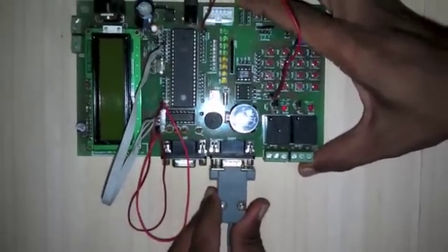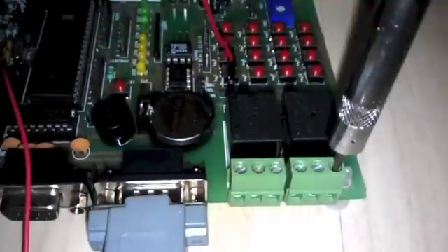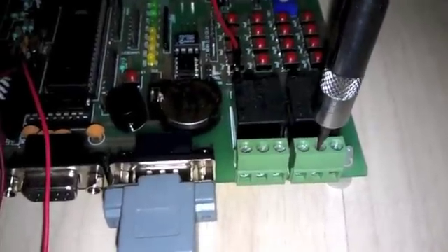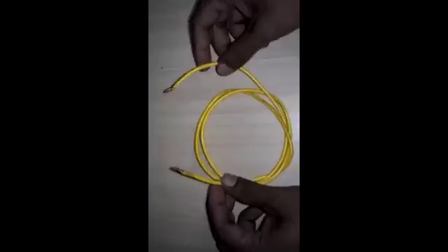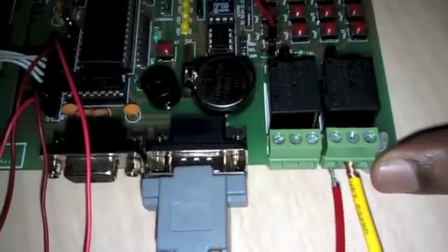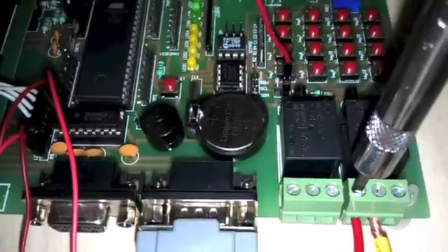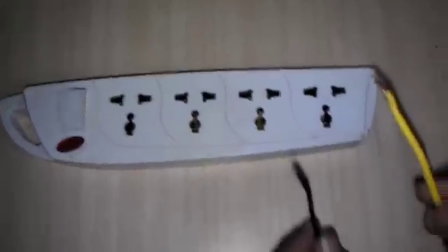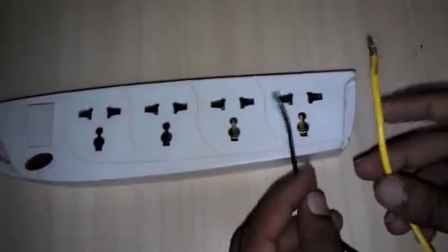What about the AC light bulb? Let's connect it to our relay number 2. You will need a bulb holder and a twisted wire connected to it, like this. You will also need a separate insulated copper wire, like this. Now connect one end of the separate wire to the center relay connection, like this. Connect one of the bulb wires to the left relay connector, like this. You will now be left with two free wires, one from the bulb, and the other from the separate wire used.